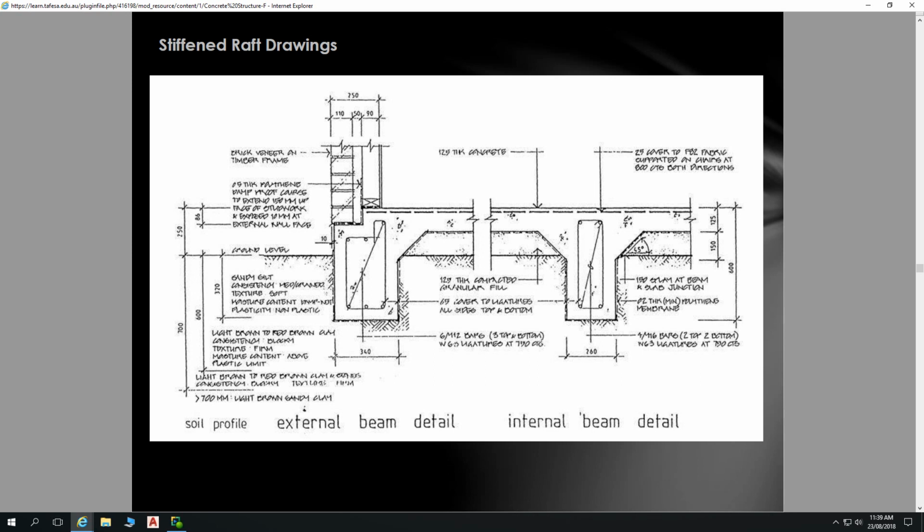The ideal thing is to be placing concrete on an overcast day. Daylight, not a lot of sun, not really hot. You're not going to have concrete going off really quickly, but no rain. You don't want rain on your concrete. You don't want water messing up that top surface, because it dilutes the cement on the top and makes the top weaker.